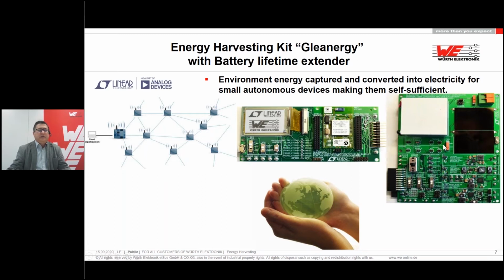You have here a power board where you can harvest thermoelectric, you can harvest solar cells, you can put the solar cells in parallel and serial, and you can connect inductive or piezo harvesters. The DC-DC converters on this energy board are so smart that they do the energy management by themselves. They can harvest multiple sources at the same time. They have an output for a capacitor bank or a supercap. You can put one output to a lithium polymer to be recharged.